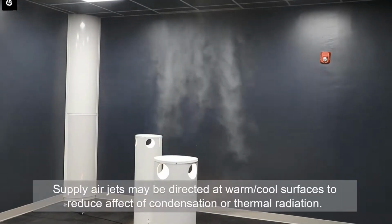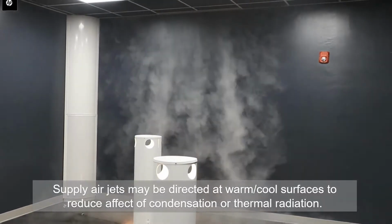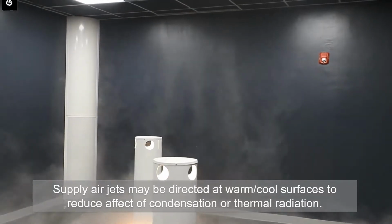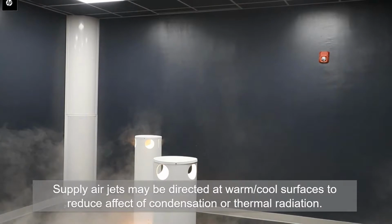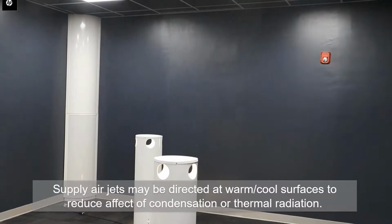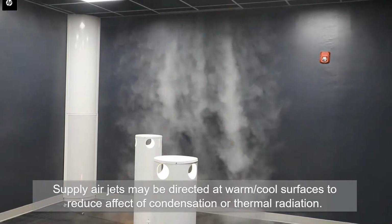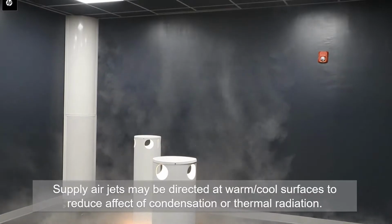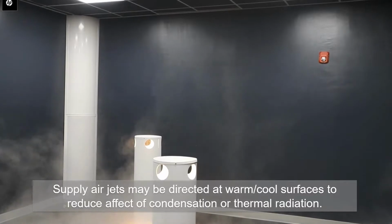It can also be to our advantage to supply air directly onto exterior wall surfaces, especially windows, any place that has a warmer or colder surface temperature. When we have warmer or colder surfaces, those can create thermal radiation effects, which will be uncomfortable for occupants. And if a surface is too cold, it can create condensation, which is moisture, and can lead to moisture damage if left untreated. Supplying air directly onto those surfaces helps normalize that surface temperature such that our occupants no longer perceive the radiation, and it removes the risk of condensation.